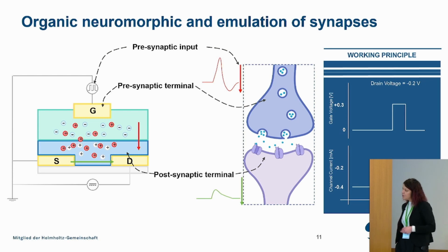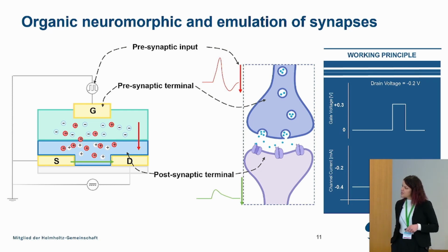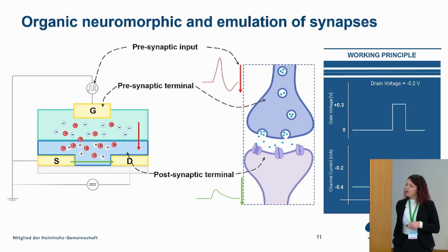And this is actually what we did. So we had living neurons now directly in contact. Just for optimizing the interface, we used a microfluidic device together with the organic electrochemical transistor. And so what we see in here is just oxidizing the dopamine, as I said. We could, applying, let's say, as an input at the gate, a train of pulses with an amplitude which would match the oxidation potential of the neurotransmitter, meaning that we would first move the cations present in the electrolyte,